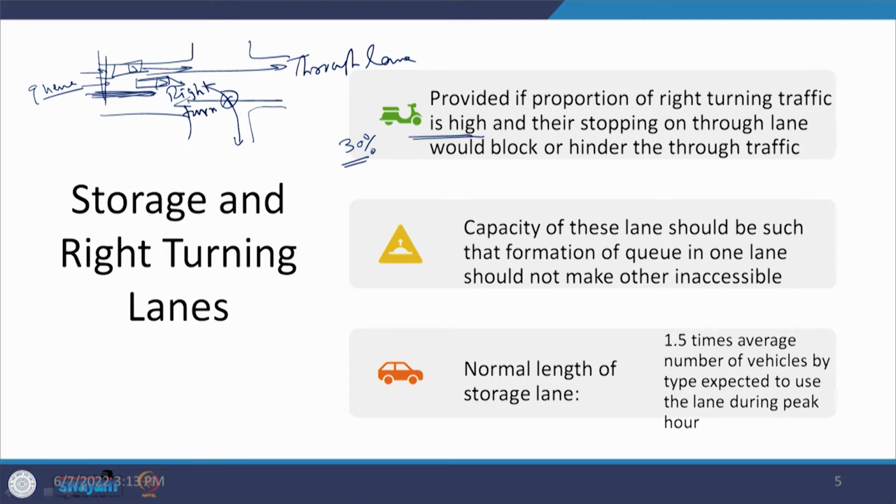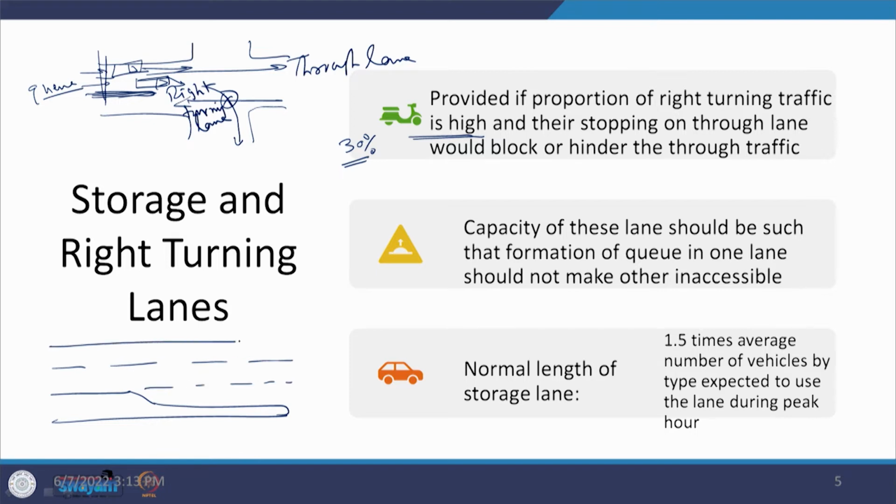and this becomes a right turning lane. So, in the form of a design, it is going to be a bit different. When we look at that and we have a median, this is how it is going to happen. So, we have the through lanes here, and a median is being provided. So, we are providing the opportunity for the through traffic to keep going ahead, but there is a movement for right turning, and the right turning traffic comes here and waits on this particular lane. So, now whatever queue formation is there, that is in this right turning lane.